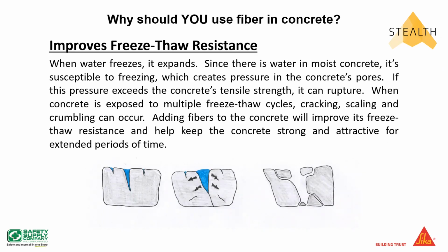Another big thing that it does, it improves the freeze-thaw resistance. As concrete is porous, and when it's moist, wet, whatever you want to say, in cold temperatures, probably not a big deal in Barbados. I don't know what the low temperatures get in Barbados. Probably not a lot of freezing temperatures, I wouldn't think. But here where I'm at, we see freezing temperatures all the time in the winter. So when that water infiltrates these pores and it freezes, well, it does just that.